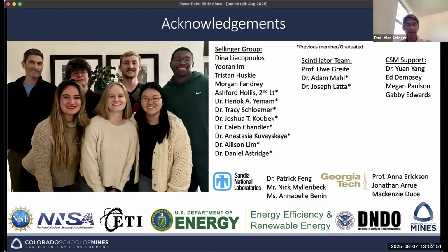Especially when we're making new dopants, they need to be very, very pure. If you think back to one of my earlier slides, when I showed that you only need 0.1 weight percent of the secondary dopant to funnel all the energy out, that means that 0.1% of an impurity can kill everything. In this case it's 0.1% of something that you want, but it could easily be 0.1% of something you don't want that could kill your whole process. So purity is really, really a big deal.